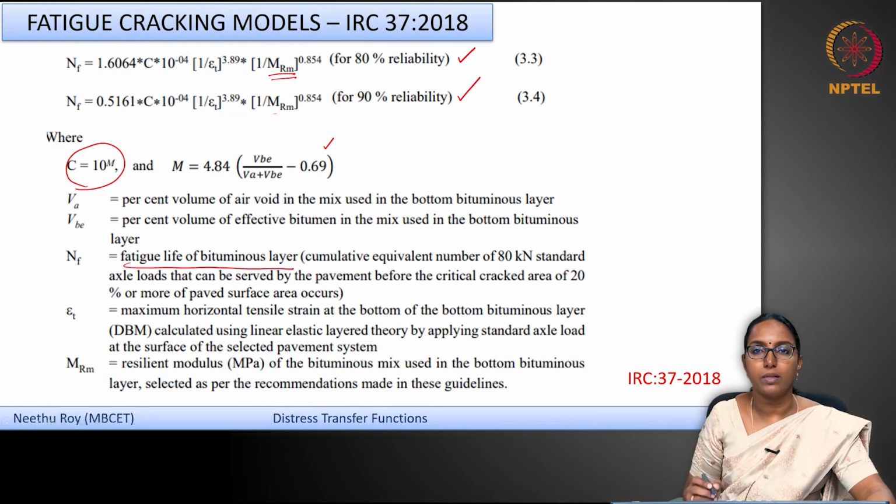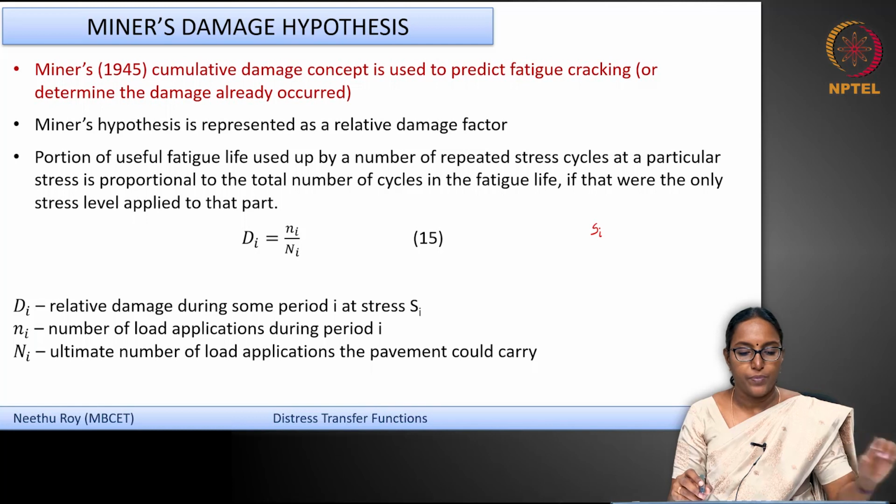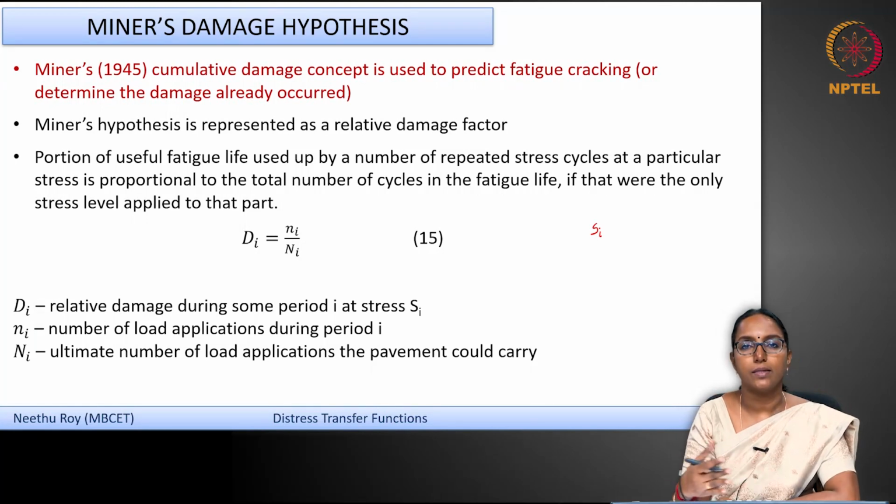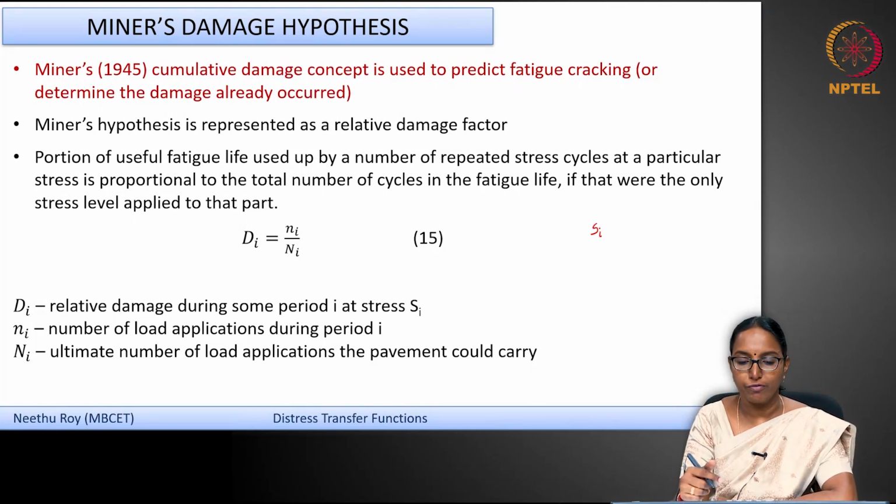Now, what is the loading that you have to consider? You have to consider the equivalent standard axle load of 80 kilonewton, that is a single axle dual wheel, that we have already discussed in traffic. Okay. Now, this damage that accumulates over a period of time due to fatigue, or the fatigue cracking damage,